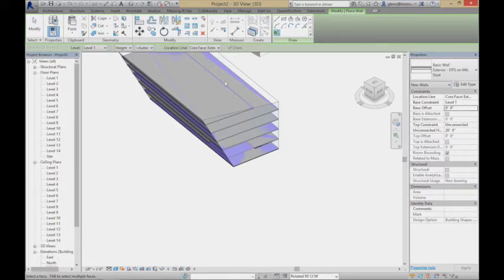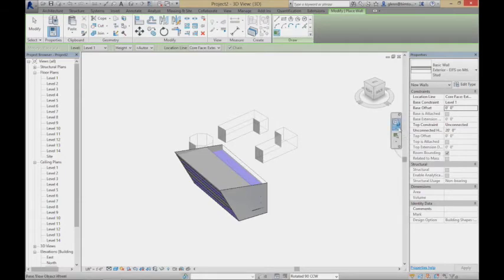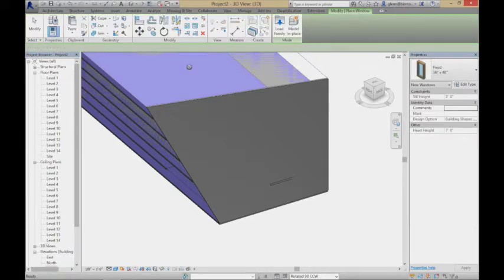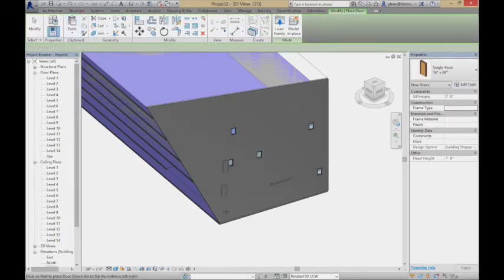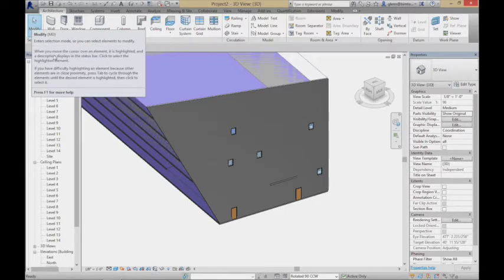That's the notion of what surface of the wall will be right where the boundary of that mass is. Is that boundary of the mass the outer side of the skin, or is it the side of the structure? I can put a wall right there. And I'll put a wall on this side. And again, these walls are every bit as good as the walls that you created other ways. So for example, if I want to put some windows in, some doors in, whatever it is, I'll apologize again, it's going to be an ugly building. But I can use this form to generate those things.